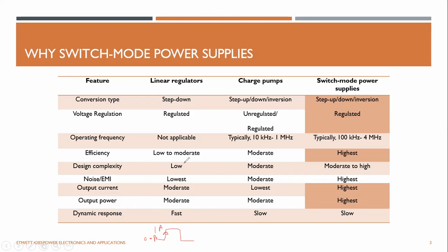This tells how the output changes, right? No matter how you change your load, you're expecting, let's say, a 5-volt output. But the time that you switch on your load, the output will go down and then settle there. And if you turn off the load, it will go up and settle like that.